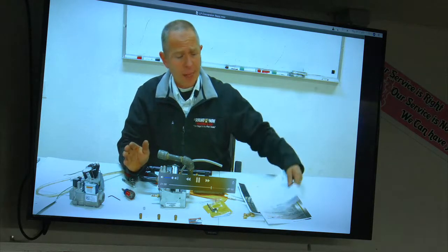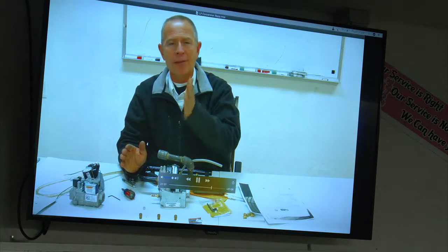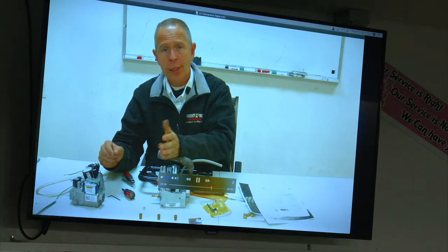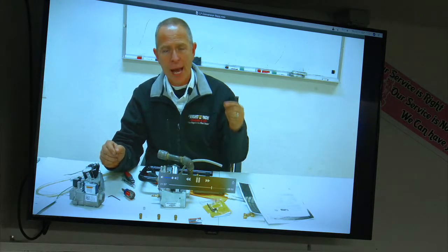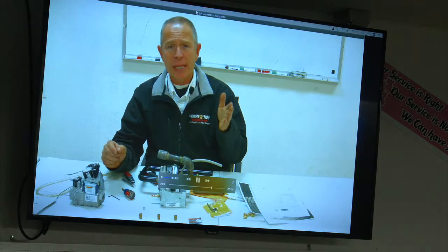Then we need our supply temp. And our supply temp rule of thumb is this. It needs to be right out of line of sight of the heat exchangers. So we would not put it right below the coil, because that's going to radiate and actually make the temperature higher than it actually is. We need to be out of line of sight.